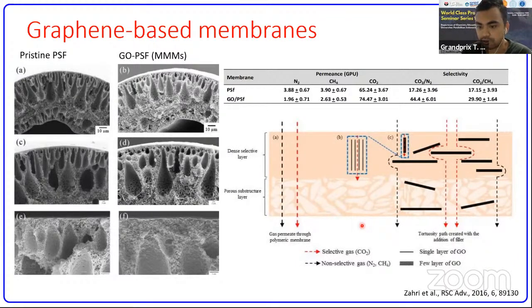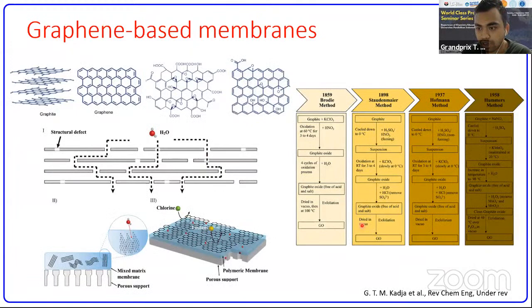As I've mentioned before, this is the layer of graphene horizontally aligned. It could create new interplanar spacing, acting as a separating layer. But we cannot control the orientation of the nanosheet layers within the continuous phase of polymers. But it would not be a problem. Why? Because either horizontally aligned or vertically aligned, they could well act as the separating layers.